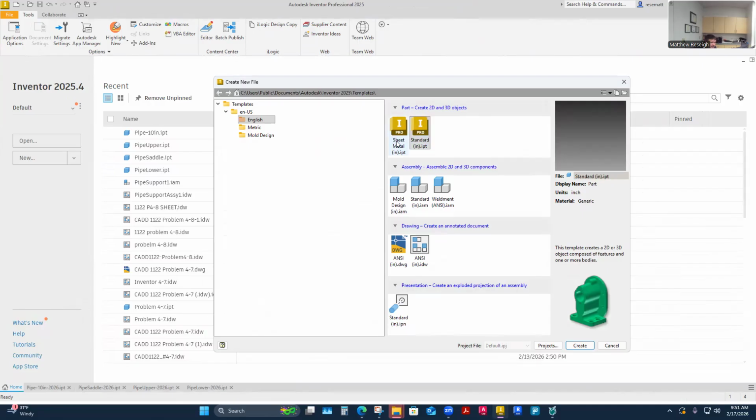It's like here's my sheet metal. It doesn't have any bending or rolling, but it still is a piece of plate that's going to be lasered or plasma cut. So it's going to have just a 2D cut file is what I think of. That's the whole point of that saddle piece and making a flat pattern, it makes your drawing just a 2D drawing to cut that. And they'll load the correct thickness of material to get their 3D. Same thing with this base plate. It's just 1/2 inch plate, even though it has no bending or rolling or whatever.